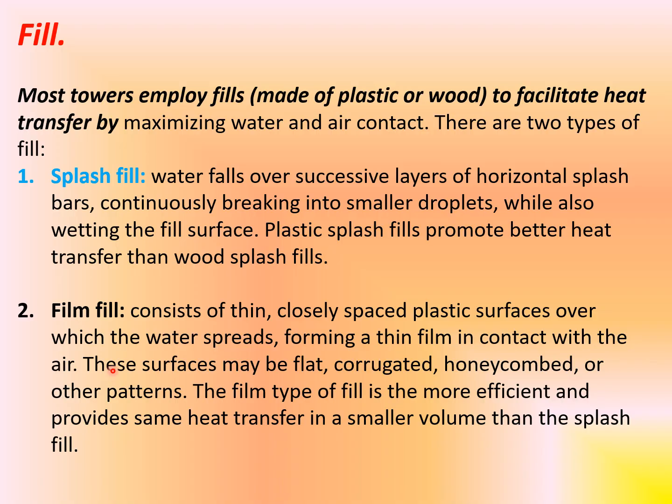These surfaces may be flat, corrugated, or honeycombed, or of other pattern. The film type of fill is more efficient and provides the same heat transfer in a smaller volume than the splash fill.